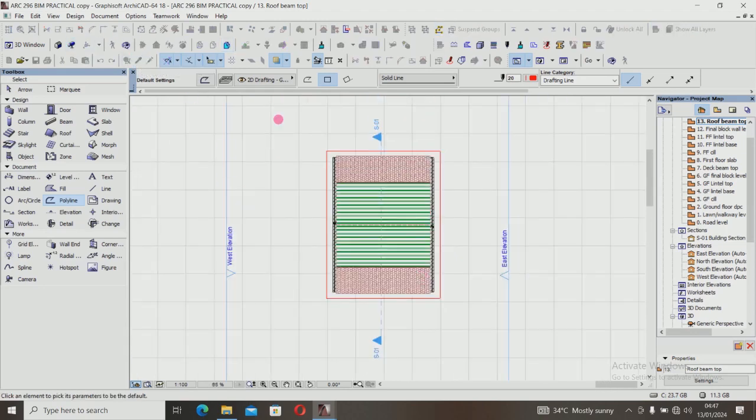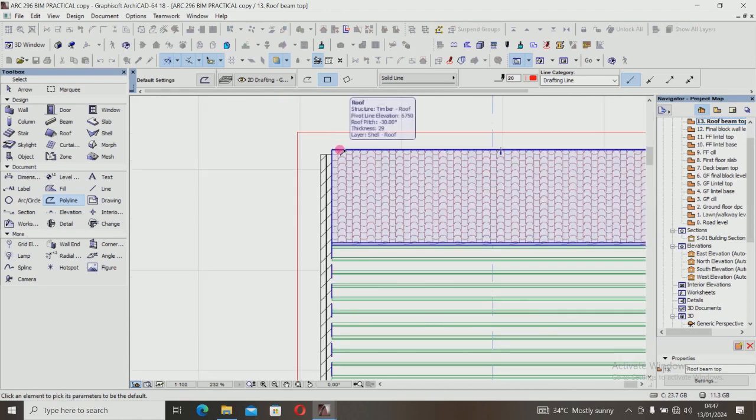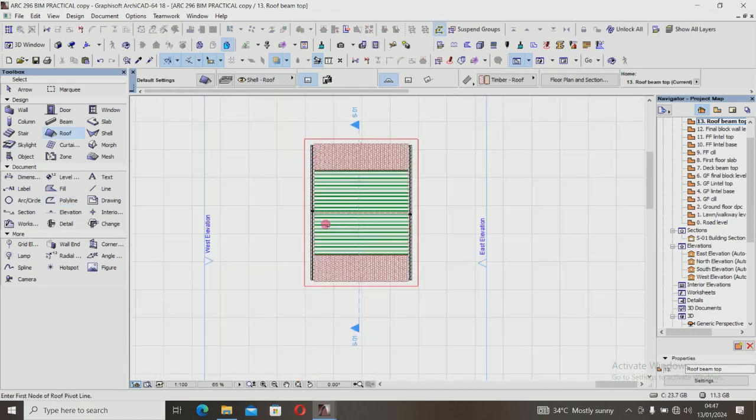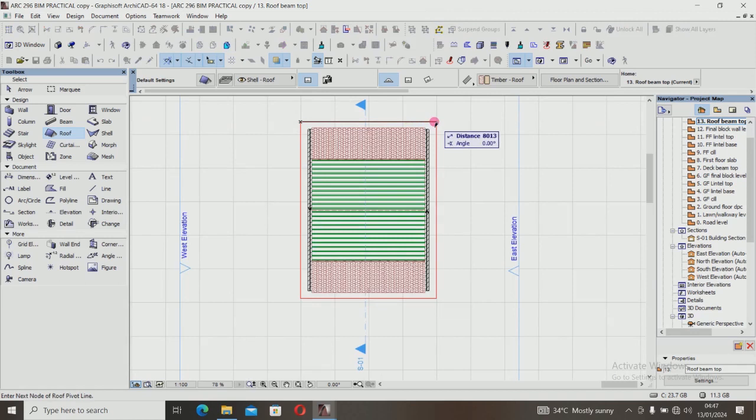Then use your pick parameter and pick this particular roof here. You know, this is a manual roof. Draw a line at this place. Use this direction as your arrow, the direction in which the roof will be draining rain. Then pin at this point.